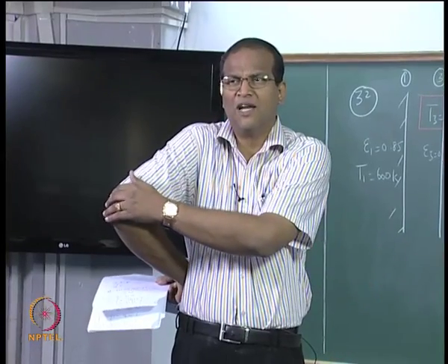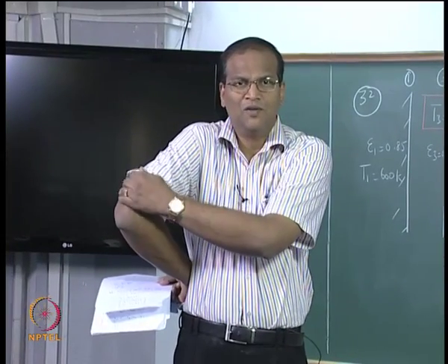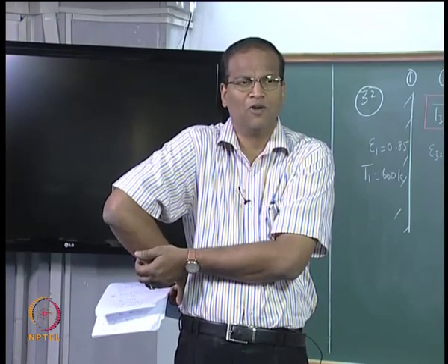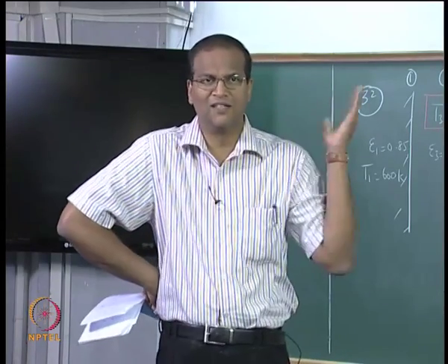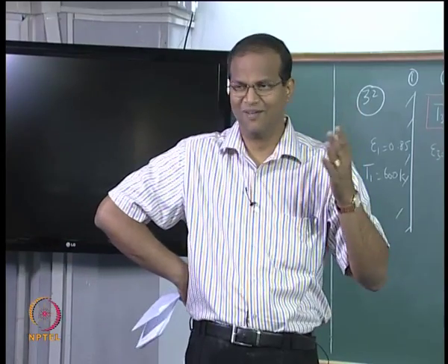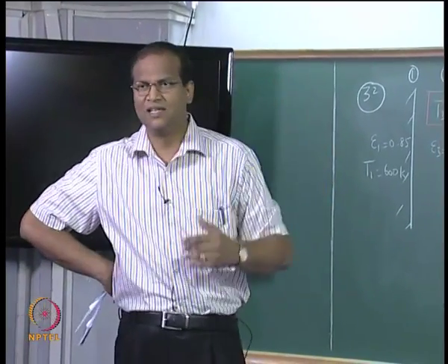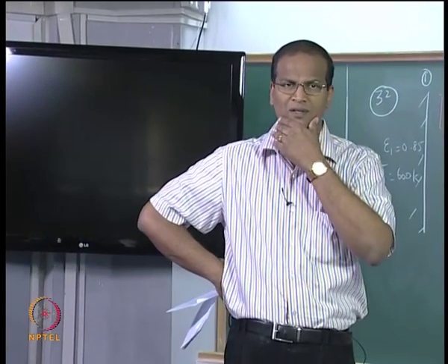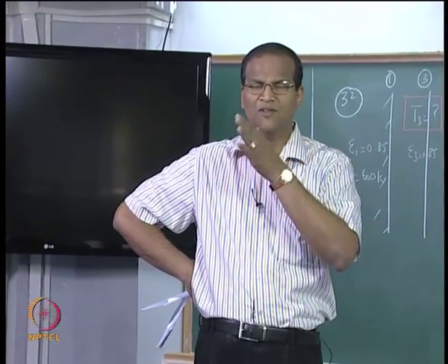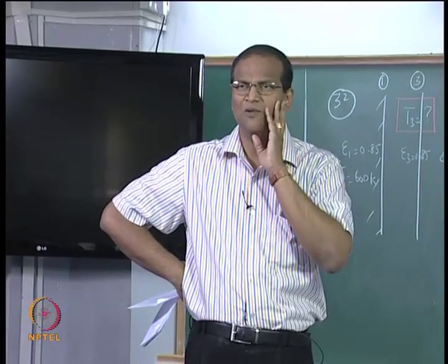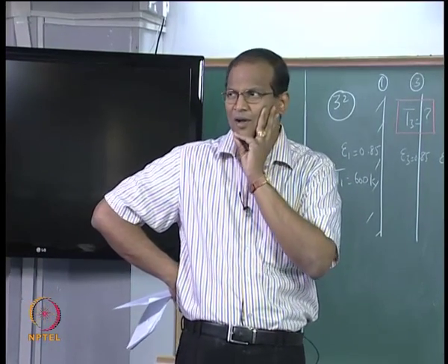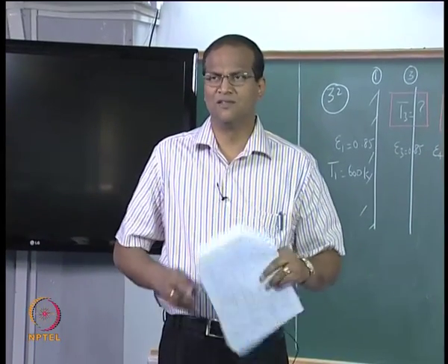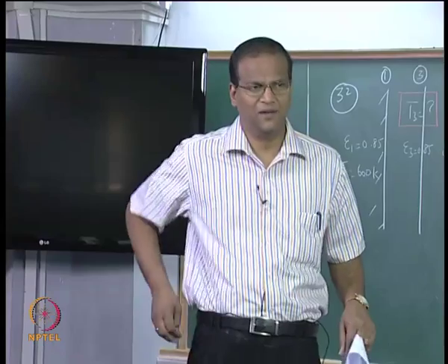So you will get an approximate idea of T1 to the power of 4 plus T2 to the power of 4 divided by 2 whole to the power of 0.25. Do not take it as the formula, only if the two are black and other things. This is asymptotic case. Always when you do some engineering analysis, you must look at the asymptotic case. What happens if both are black? What happens if emissivity is 0? What happens if T2 is equal to T infinity? Somewhere you must get an answer which is consistent with your common sense. Then you know, okay, this must be right.